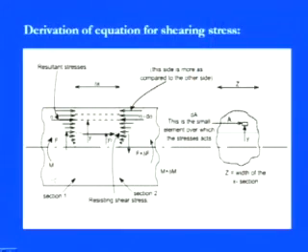You can see this particular diagram, as we discussed, a simple straight beam with this cross section, and this particular section is influenced by a shearing force. After a segment delta x, the cross section has shearing force F plus delta F, and we have the bending moment in the sagging form, M, and on the other side after delta x we have M plus dM.